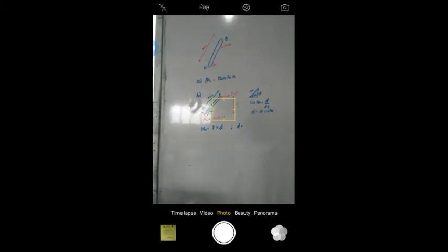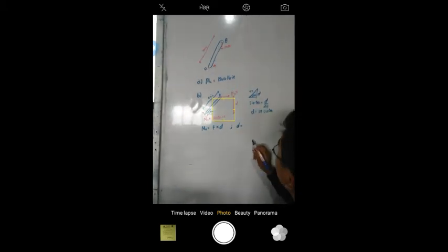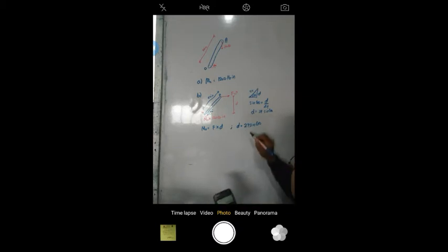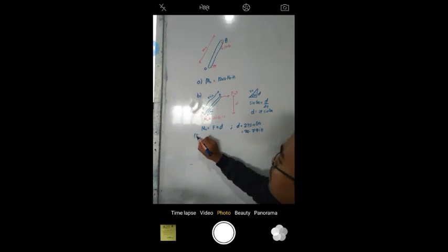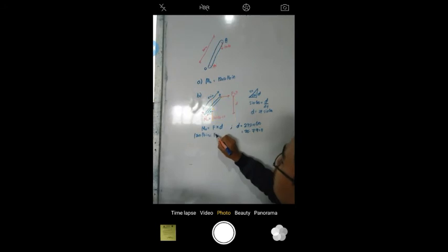So the value of D is 24 sine 60. But 24 sine 60 is what? 24 sine 60 is equal to 20.79 inches. Okay? So our moment is 1,200 pounds-inch, which is the force, which is unknown, times 20.79 inches. Since the inches cancel, what remains is pounds.